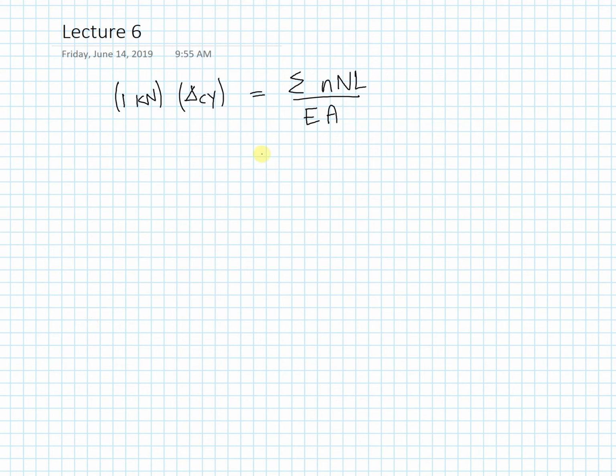And what I need to do is to really plug and play now. So I have a 3.0 here. I have my unit conversion. It's very important to be consistent when it comes to units, because otherwise you tend to get magnitudes that don't make sense. You'll have structures that will be deforming by a meter or so, and that never happens in real life.